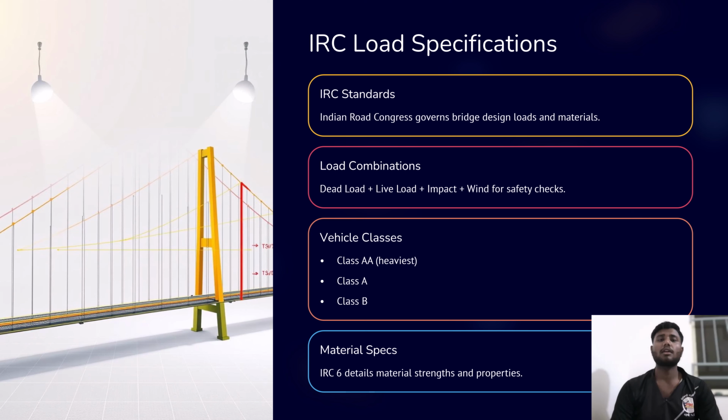Moving on, our next is IRC load specifications. In IRC standards, the Indian Roads Congress governs the bridge design loads and the materials. Then load combination: dead load plus live load plus impact plus wind, for safety checks. All these loads are combined into load combinations.